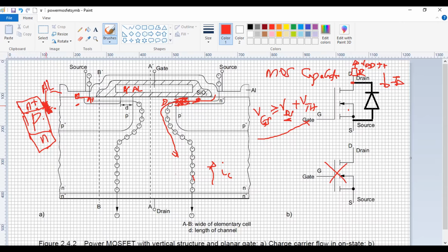That's aluminum. The effect of having this is to make sure that this is not a BJT, to get rid of the BJT, which, like I said, historically, when they were first building these devices, would switch on every now and then and create problems for you.